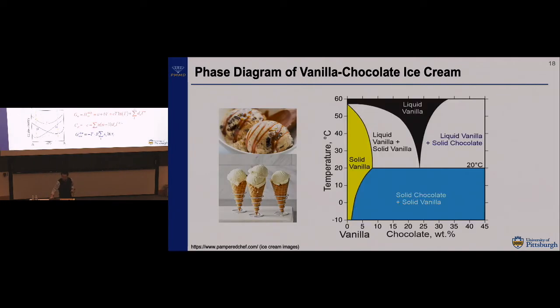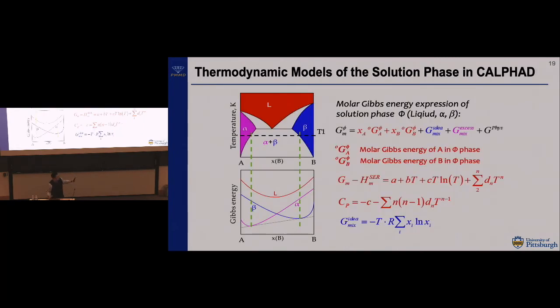So you see the phase diagram showing here is very similar, like this. I just make a simplification, okay? So basically what we have is A component, B component, and here you have liquid, and alpha, beta could be different solid phase, all right? So you start to have the so-called eutectic reaction, okay? Liquid will decompose to alpha and beta.